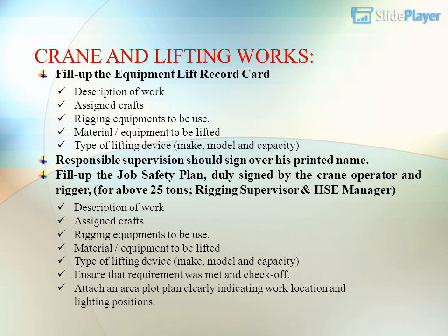Crane and lifting works: fill up the equipment lift record card. Description of work. Assigned crafts. Rigging equipment to be used. Material, equipment to be lifted. Type of lifting device, make, model and capacity. Responsible supervisor should sign over his printed name.